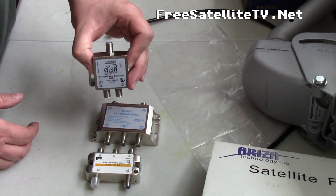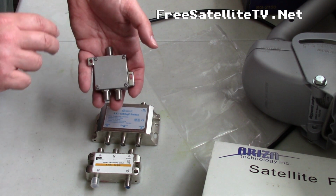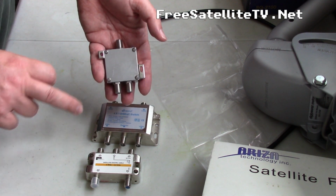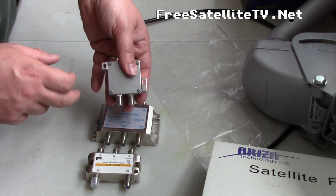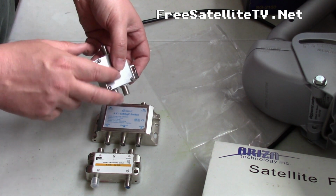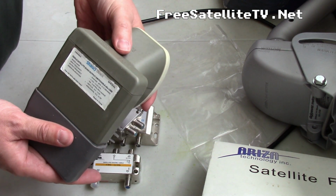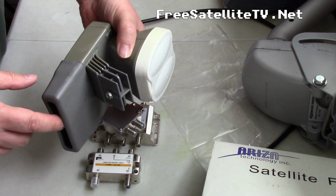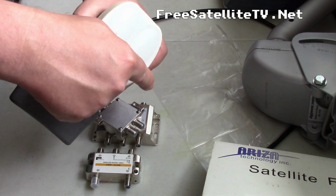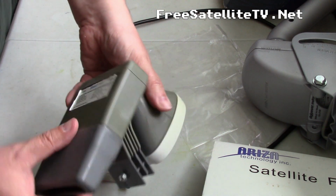Now there's other things like this that are not this. I'll just turn this around and we'll ignore it. I don't have one with me anymore, I can't find it. It's a 22K switch. So you might see in your receiver 22K on, 22K off. What that typically does is turn on the switch inside one of these things. If you have one of those Shaw Direct LNBs, the 22K switch on or off will switch from this LNB to this LNB. So some of these LNBs will have a 22K switch built into it.